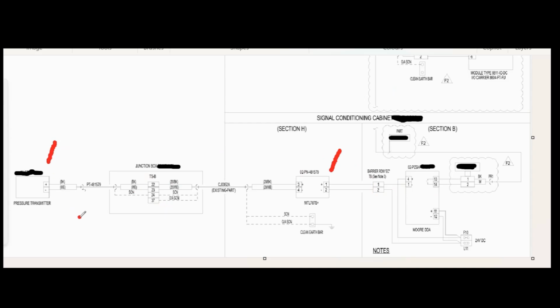Now, of these two, the pressure transmitter has a pressure supply to it, so it has a process impulse, and it has an electronic output to it. So there's a lot going on with this device. Even if there's something blocked, or because it's out on the plant, in the field, and not in the control room, it means that other people are in the vicinity. Somebody could accidentally hit it, they could knock it, they could walk past it and hit it with a scaffold pole or something. All these things could happen. So the first place that you really want to look in the event of a fault code is to check the transmitter itself.